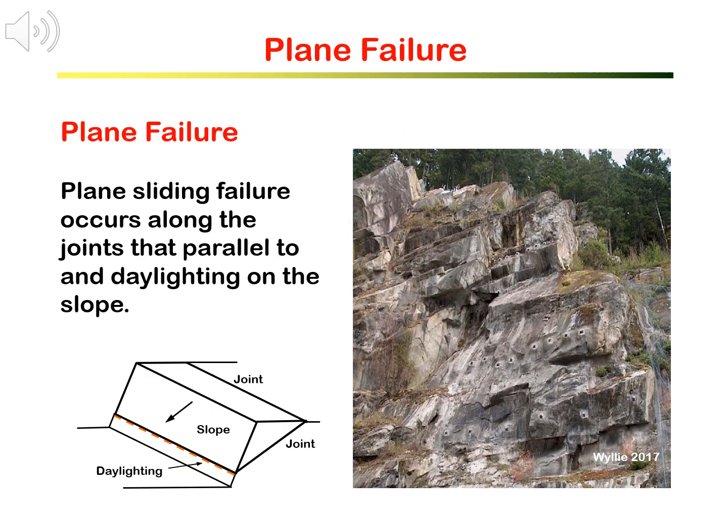As we learned in rock mechanics principle classes, rock masses are characterized by discontinuities, such as joints and bedding planes. If a bedding plane or a joint set cuts through the slope, as shown in the drawing and the photo here, we will have plane failure.